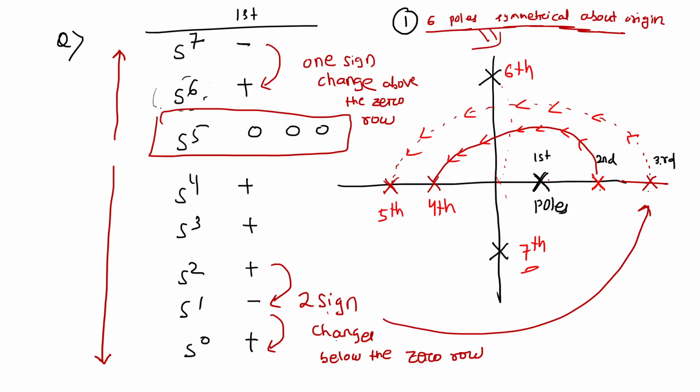This one. First, sir, the pole. If I first, where do I need to place it? Above the origin. But if you place it here above the origin, then it's a complex pole, right? Yes, sir. So you have one complex pole that doesn't exist. Complex poles always exist in pairs, right? So you cannot place that.